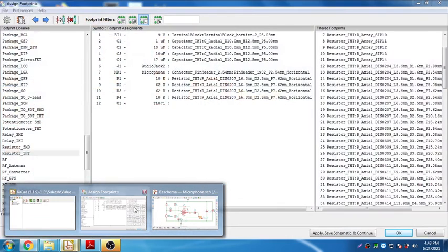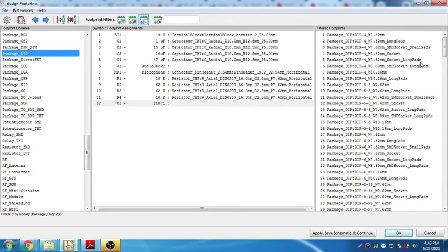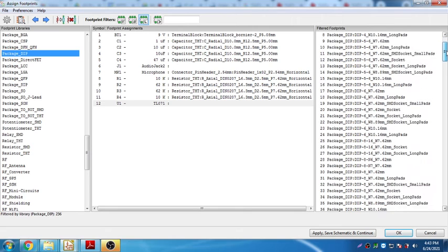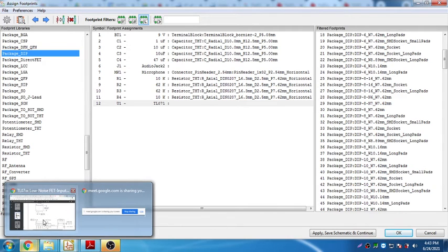Okay, just come here to the KiCad. How do you search the package? You look at this package and find the package with the dip, quick package dip. Under package dip, select PDIP package dip with the 8. This one, this section 8, and you see different ones like 16 and underscore W 7.62, all that information actually refers to some of the physical dimensions of the IC. Okay, 7.62. Look at the data sheet carefully which you have here.